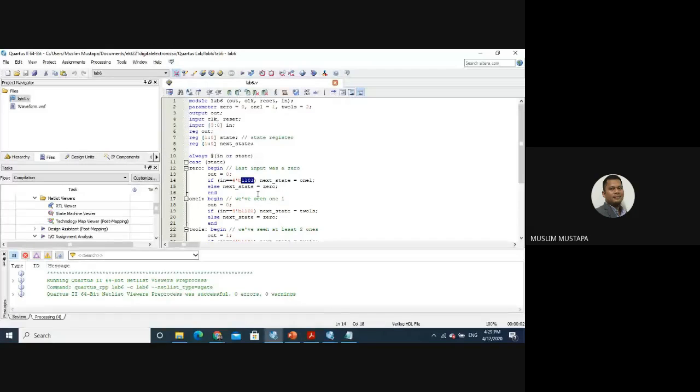The first is having one 4-bit input, detecting if you have the 1101 pattern, and if detected, output 1. Or you can accept 1 bit at a time, read the pattern, and if there's a pattern of 1011 in sequence, send the output high. Both ways we get marks.